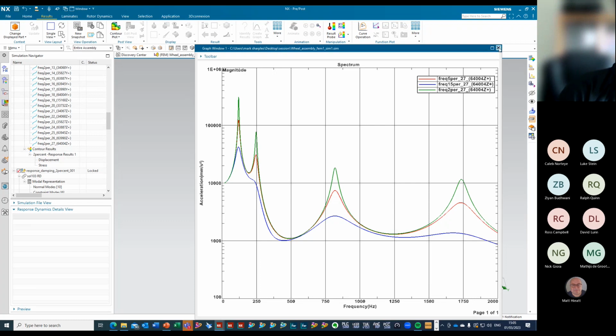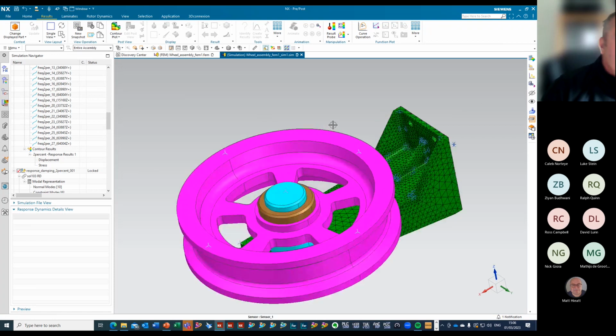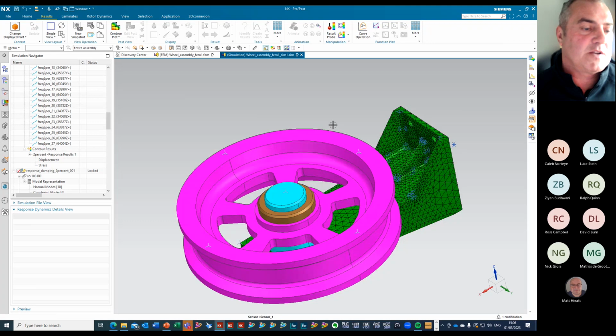Okay. So what normally would happen is, you would maybe choose the worst case damping parameter, get the values. Then when your structure is built, you might put it on a shaker, do a sine sweep, and work out what the Q is. So then that would work out the damping ratio, and then you would apply the damping ratio into your model to maybe refine your model or your assumptions. But typically for a metallic structure, it would be between 2 and 5%.